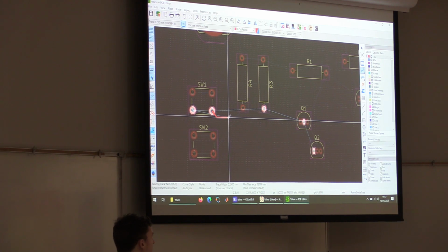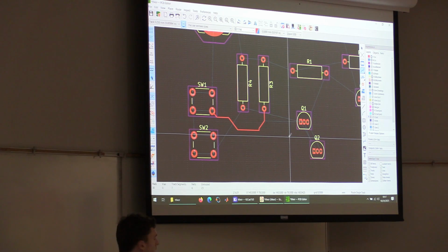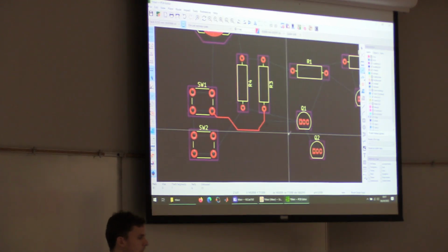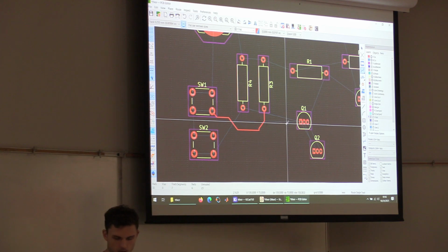And if you ever want to make a bend in a trace, you just left click and it'll create sort of a point where you can work off of. Not the prettiest trace, but it works. Now, before we place traces, typically you'd want to arrange your components the way you want it on the board. And I believe in my notes, I have my previous design that I'll follow. That way I don't get lost, because finding the right layout takes a bit of time.